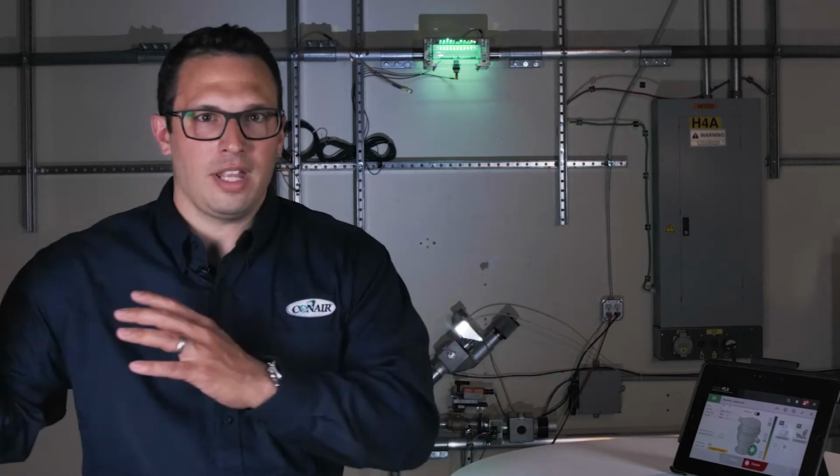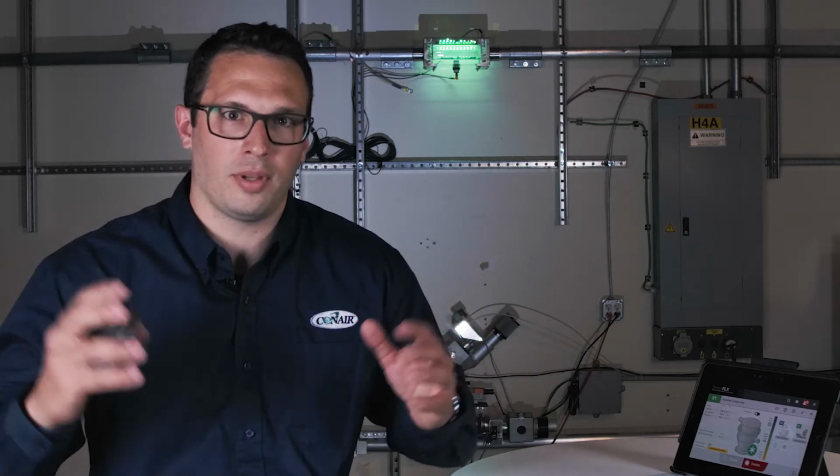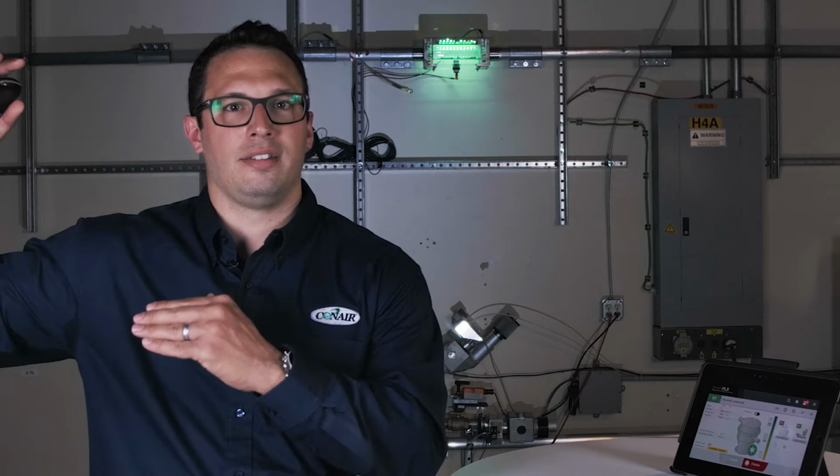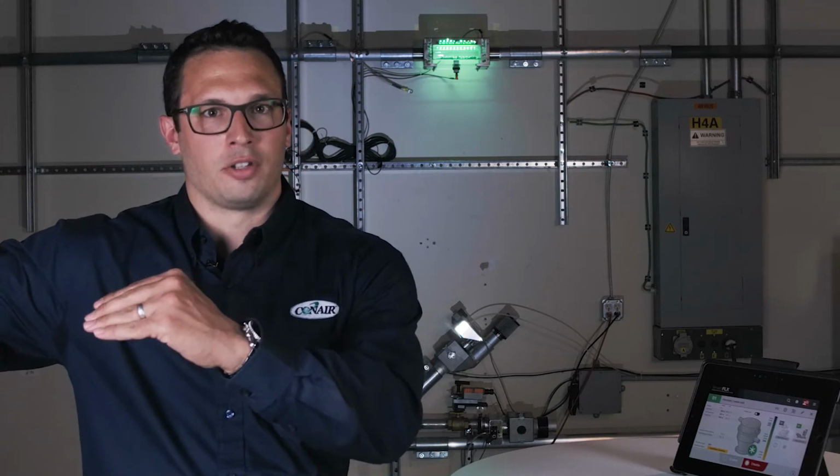With dilute phase conveying, you're at atmospheric pressure at the pickup point, and you're looking at around 10 to 12 inches of mercury, or call it 10 inches of mercury, at your receiver. So you're seeing a fairly high delta P, delta pressure. Really, it's negative in this case, but it still applies for both sides. To balance the equation out, that results in a very high delta V, delta volumetric flow rate.